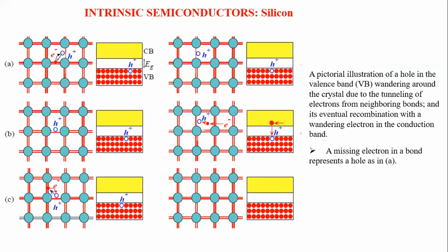Then, what is the first thing? What is the difference between a metal and a semiconductor? In metal, the free electrons are available in the lattice. So whenever you give a power supply or voltage, the electrons are ready to move towards the positive side of the battery. So what is different in a semiconductor? In metal, it is a unipolar conduction, whereas in the case of a semiconductor it is bipolar. So what is bipolar? Like we defined electrons and holes, right?